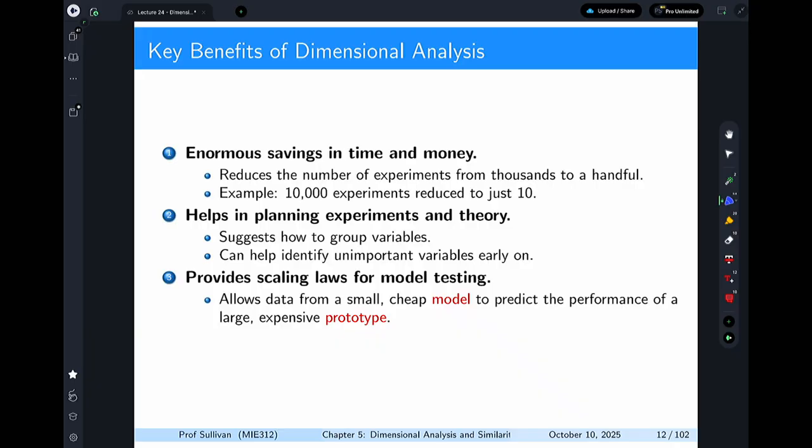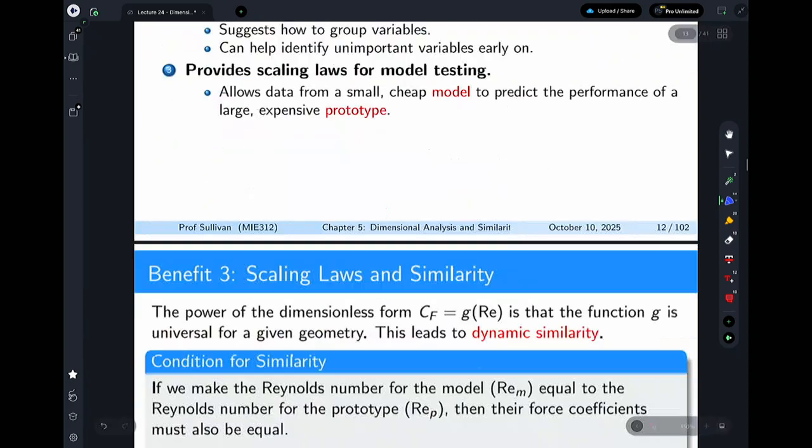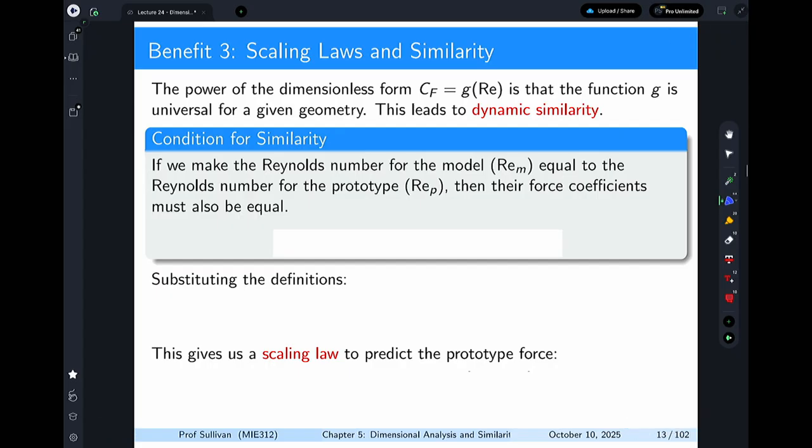Now, the funny thing about Reynolds' pipe experiment is that if I want to torture a PhD student, I will ask them to design an experiment that will get up to 50 to 100,000, which is very large, very high speed, and maintain laminar flow. And it's possible. But the problem is that if their friend walks in and slams the door, the entire experiment fails. So it's kind of neat to look at what you can do based on this information and these scalings.